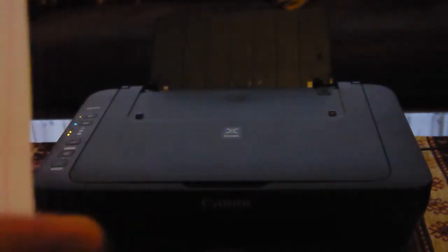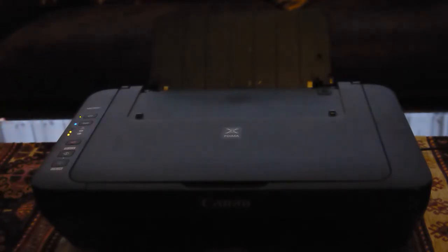To this end, you need to know which way and on which side your printer is going to print. What I recommend is printing a test of your design, especially the very first time you do it, to make sure it prints correctly and prints to the desired level using just normal paper. When you're doing that, you can put a mark on one side, and that will enable you to ascertain whether you need to put your paper in face up or face down. In my case, I've already done something like this, and I know I have to put the paper in face up.